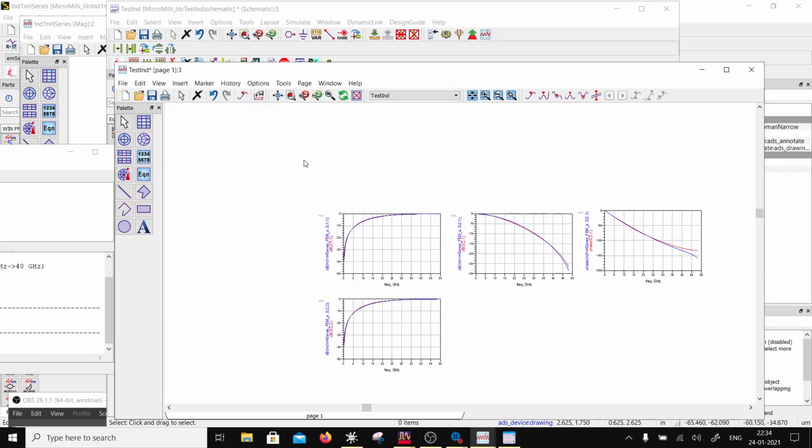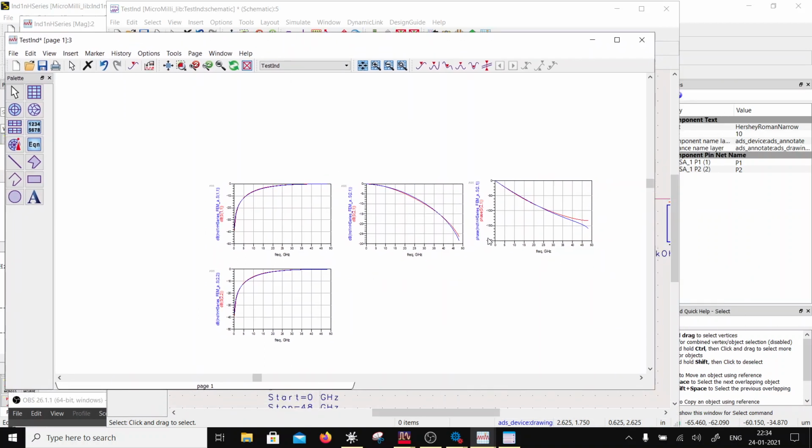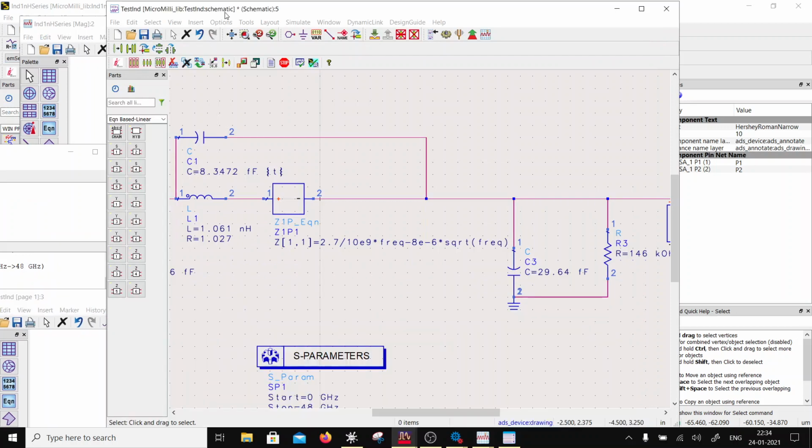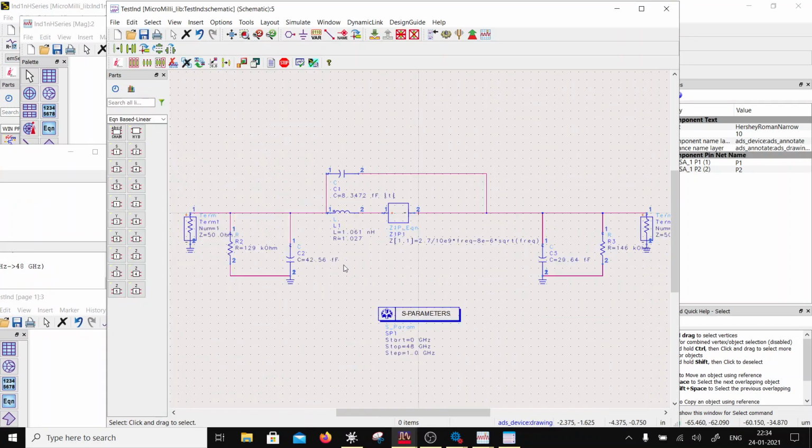Okay, so I am going to leave that model here because this is a very quick turnaround for a broadband model for an inductor. I think I can use this inductor up to 30-35 gigahertz in this inductor model, right? But what I'm saying is don't do number crunching. Don't go the deep learning way of fitting the model, where there is a training sequence and they don't even have components which have physical significance. You have to put in the model with physical significance, and that's the whole point I'm trying to prove here. Okay, so thanks a lot.